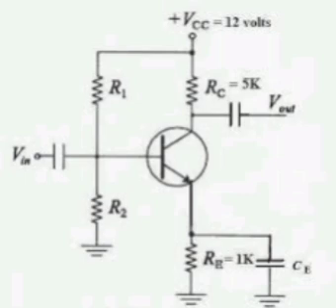Now the equation: Q phi s, that is from E vacuum to the Fermi level, equals Q chi s, that is E vacuum to Ec, plus Eg by 2 plus Ei minus Ef.